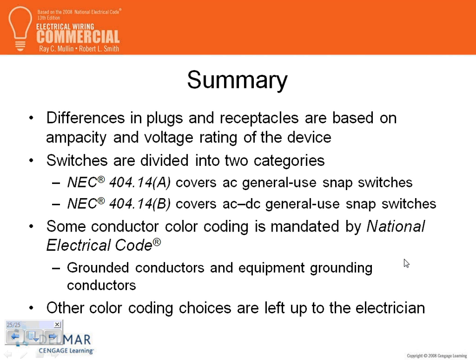I can't emphasize enough the locations where you need GFCI, weatherproof receptacles outside, and color code for the system. Very important, guys, especially if you want to take your career to the next level. Instead of being a drafter, you're going to be a project manager or estimator. It would be really nice when you walk in and a smart electrician sitting there says, oh, by the way, can you tell me what phase this is? And he's pointing at a conductor like this. Is this phase A or B or C? So it's really nice to know the identification, guys.